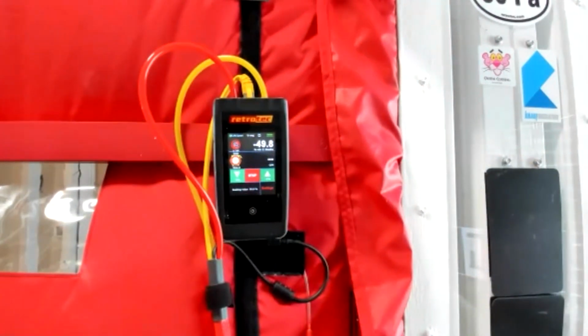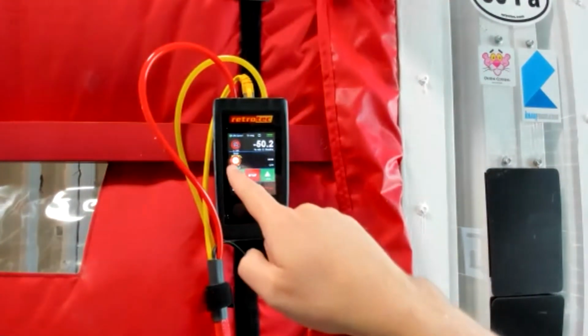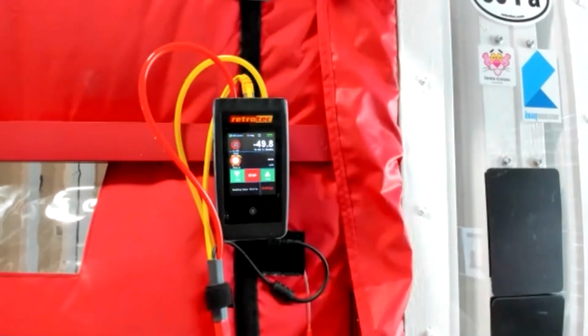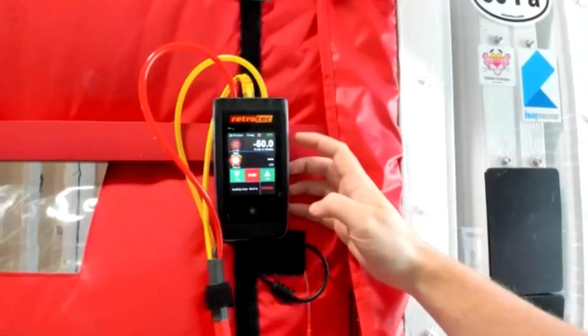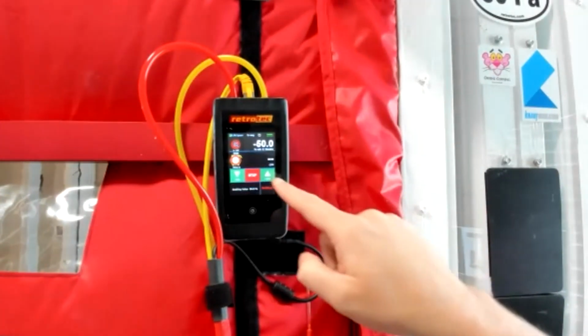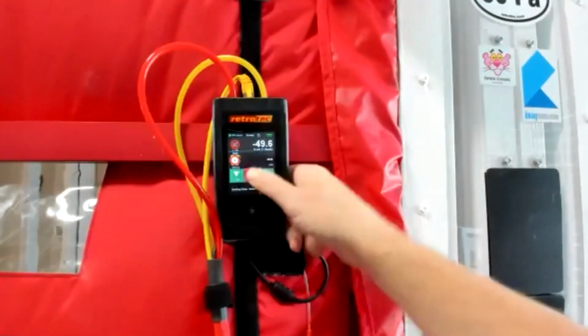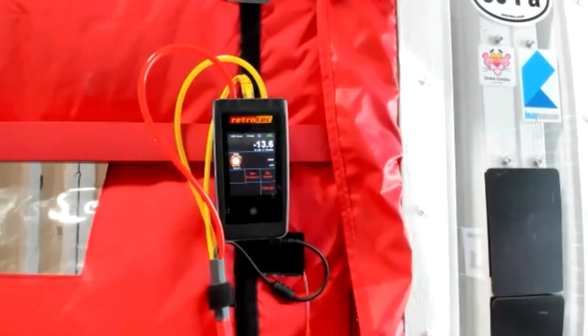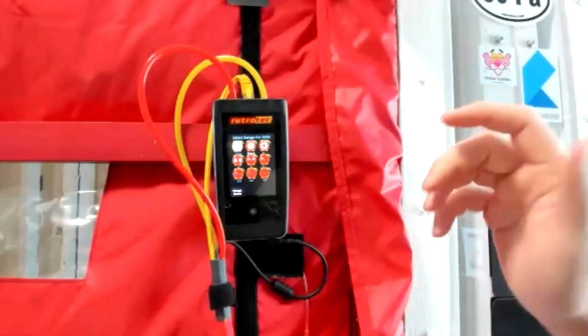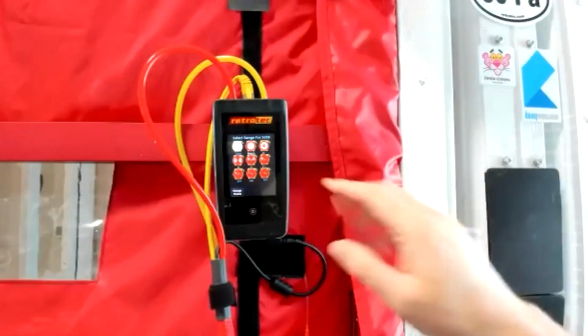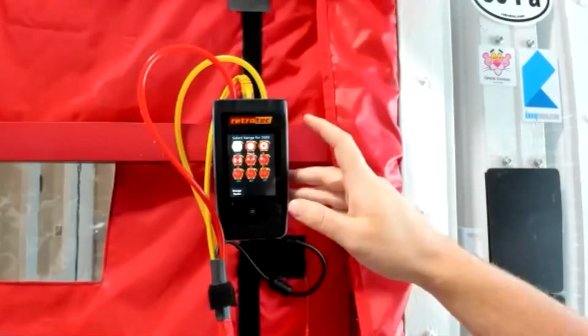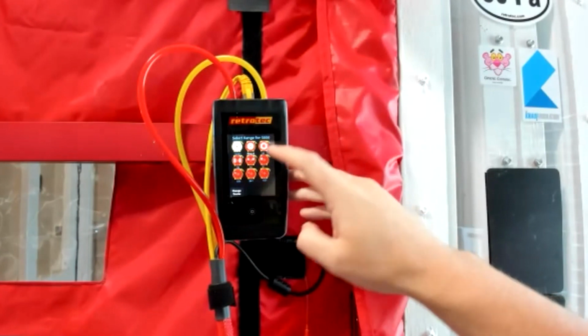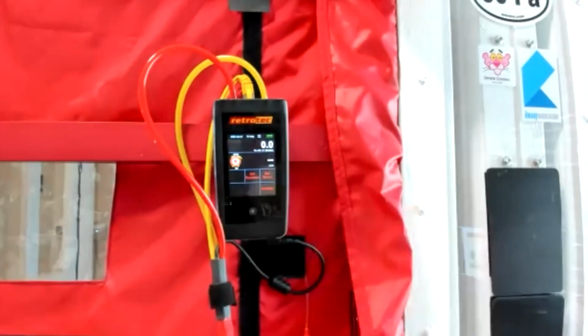And what that means is our opening, that ring A, is too big. I need to choke the fan down to a smaller range so that I can actually get a reading. The blades just aren't spinning fast enough when the house is at 50 pascals of pressure to give me a flow. So I can stop the test. The next step would be B8. So we'll try that. We'll go down to B8.